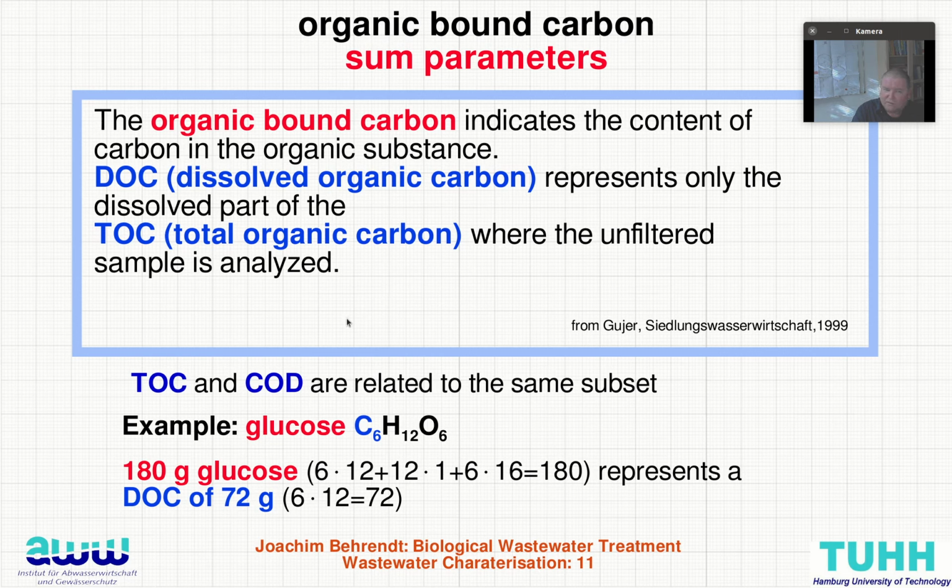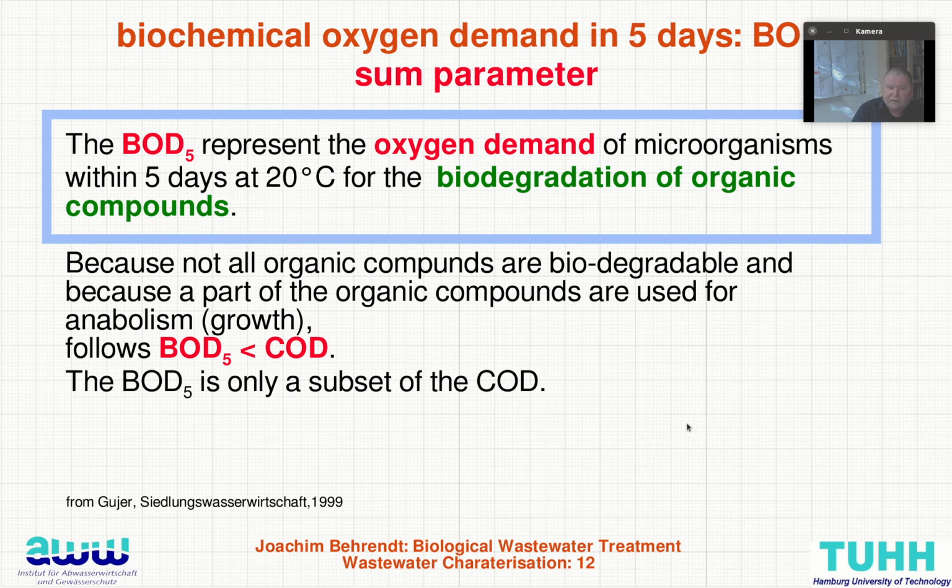Normally this is measured by incineration of this organic material, and the formed CO2 is detected after removing the inorganic CO2. There's another, mainly historical, parameter which represents the biological part. This is the so-called BOD5. This is the oxygen demand of microorganisms within 5 days at 20 degrees centigrade for the biodegradation of the organic components.